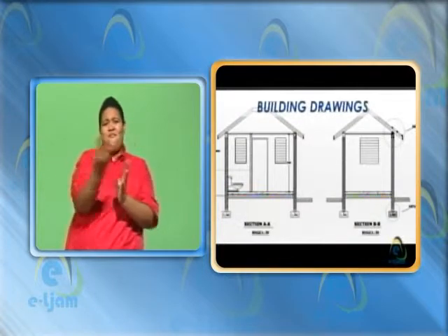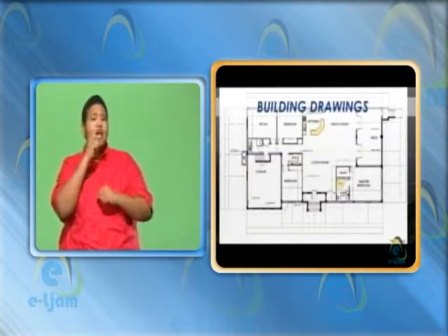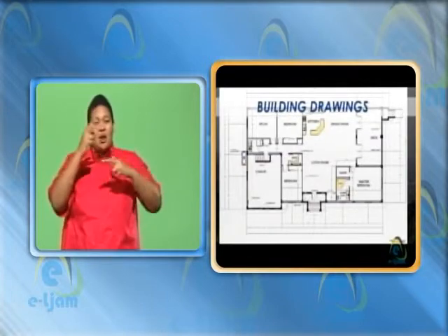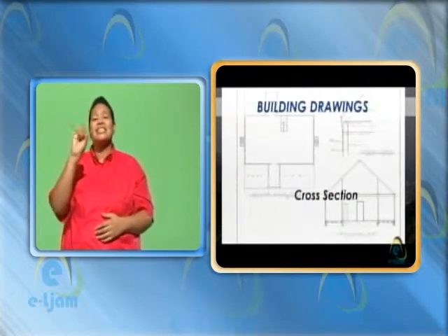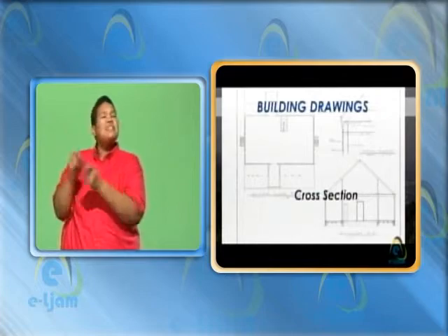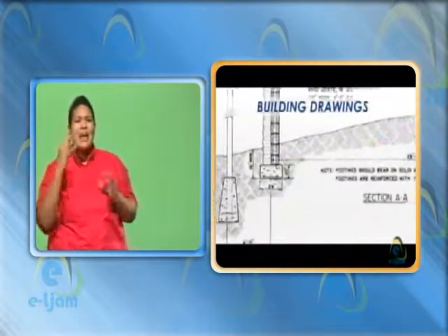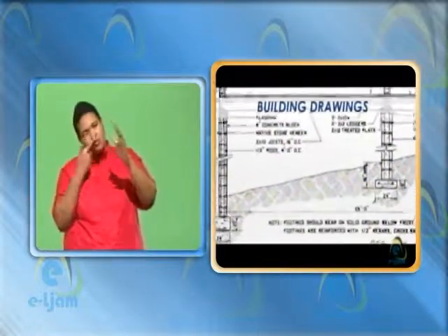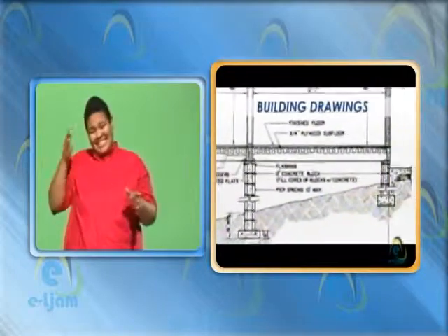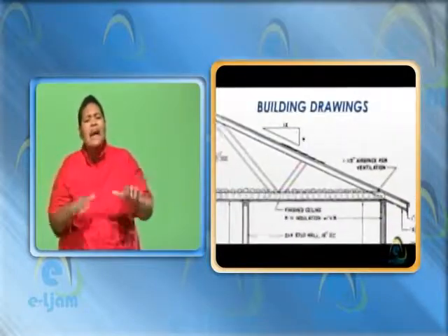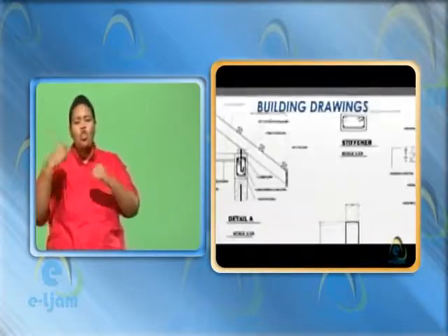Floor plan views of the structure don't always provide enough information on how the building is to be constructed. Therefore, cross-sections will explain certain special conditions more appropriately. A cross-section is basically a view of the home if it were sliced vertically through the building. This allows one to view the home from the side and understand better the relativity of varying floor heights, roof framing, and other structural elements.